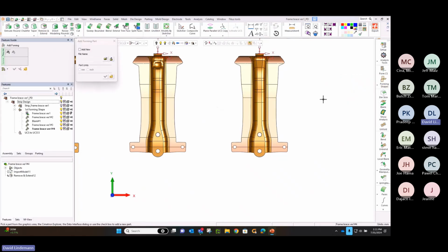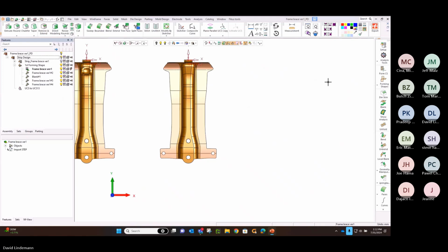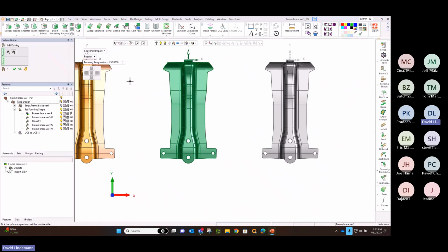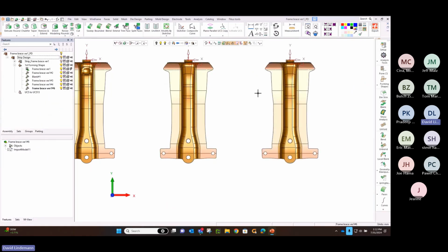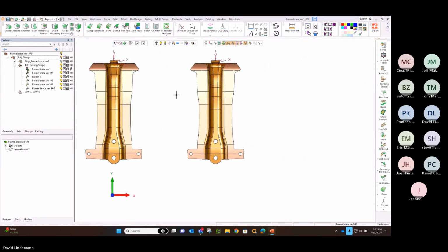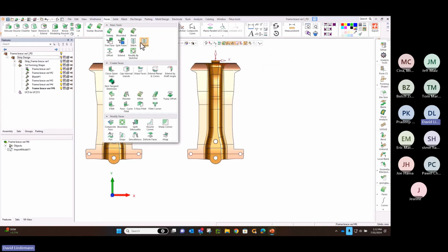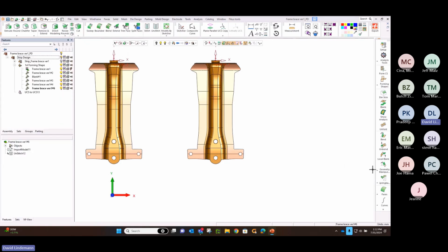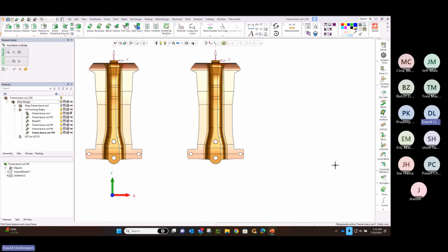Moving on to the next one, and now I've got the inside of that groove or trench, whatever you want to call it, to work with. So let's work with that next. And you can see just moving down the line. Let's make sure that I've got that little tail where it's connected. I want to leave that out of the form for now, but we're going to again do a blanking operation, I guess is better to say, where I'm just pushing the shape of these faces down onto other faces. Take the middle and let's do the left side first.